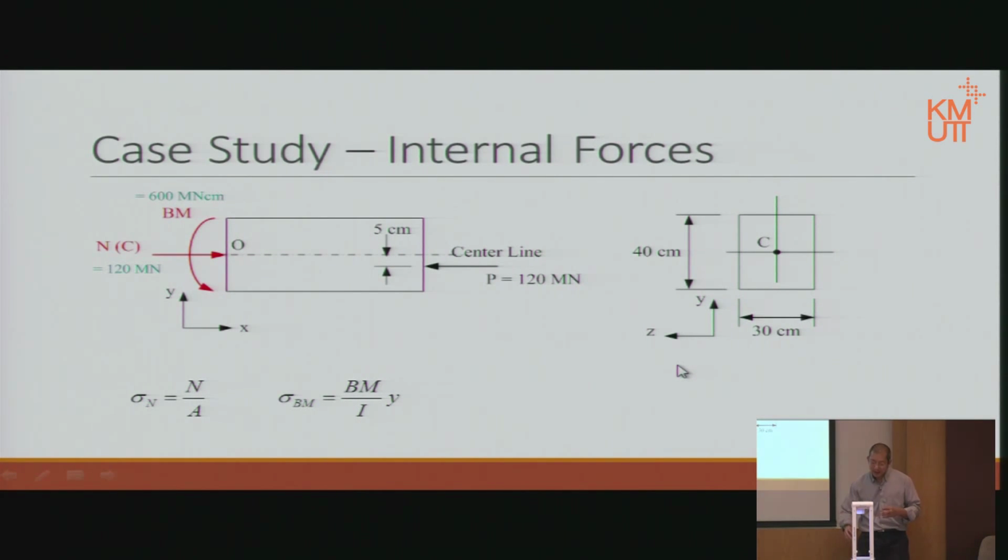Now this bending moment that we draw on the 2D plane will have to be around the Z axis. Therefore, our neutral axis must be on the Z axis as well, and it must go through the centroid. So that is our neutral axis. Everything we measure will be from that line, at 90 degrees, for the bending moment stress. The area, then, we calculate as a normal rectangle.